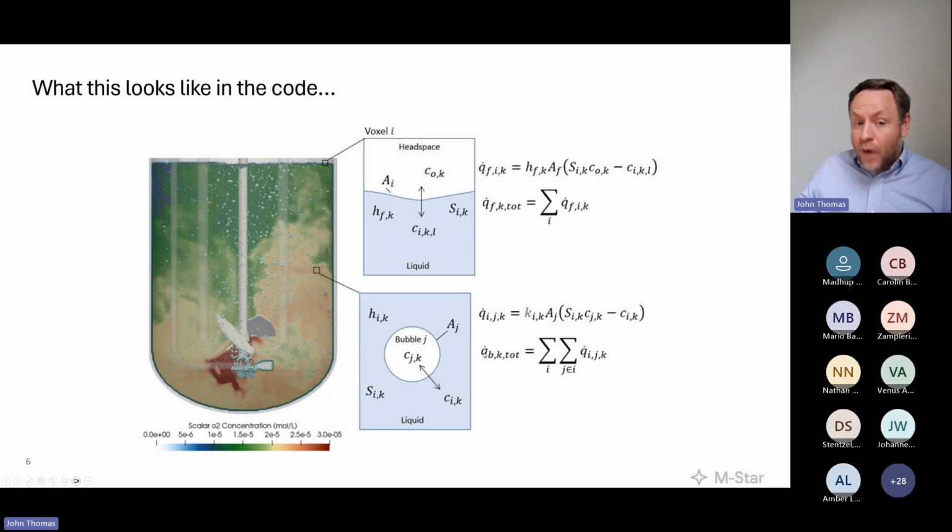If I divide that by fluid volume to get a concentration, I could recast this as an area per unit volume of fluid, as it were. So this is represented in meters per second, meters squared, moles per meter cubed, right? You see the dimensional homogeneity here. Meters per second, meters squared, moles per meter cubed gives me moles per second. The sum over all these, moles per second. If I want moles per liter per second, I divide this by system volume, which is why the V gets tucked into the A, and we arrive at a lowercase a, an area per unit volume. But either way, both approaches are fine. And that's how we often think about mass transfer in these bioreactors.